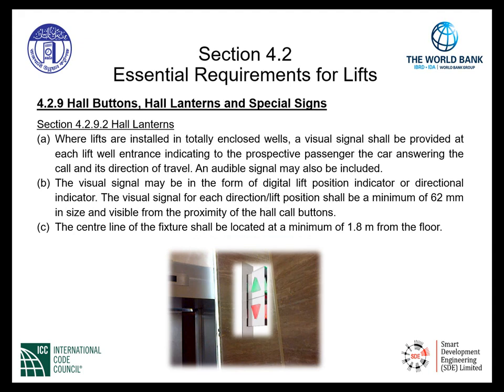The next section, titled Hall Lanterns, is given to us specifically in section 4.2.9.2. Item A indicates where lifts are installed in totally enclosed wells, a visual signal shall be provided at each lift well entrance, indicating to the prospective passenger car answering the call and its direction of travel. An audible signal may also be included.